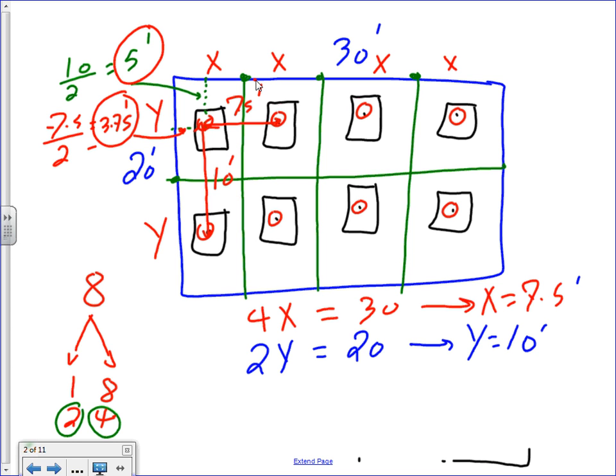Now, I'm sure Jeff is looking at me and saying, you lost it, Chad. How about the grid? If this is 3.75, it's not going to match the grid. These are guidelines. If you don't have a grid, that's how we place them. If you have a grid, then you shift. Suppose they have a grid and you are going to lay out this one. From the top, it's going to be 5. So I'm going to come from this, 2 plus 2, 4, half of this 5, and start. You might not be able to start at the half, so you have to shift it to the other. Long story short, guys, if you have a grid, you have to readjust these numbers to match the grid. If you don't have a grid, then you just put them exactly where the numbers are coming.